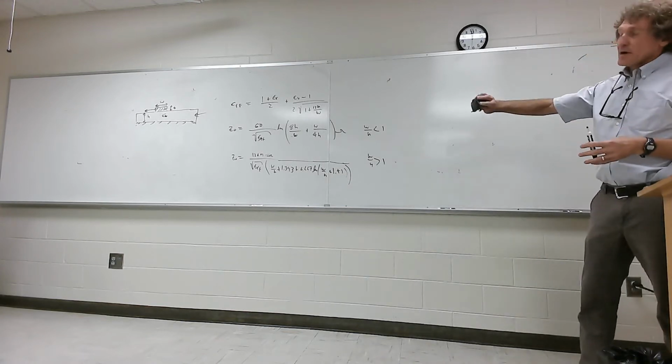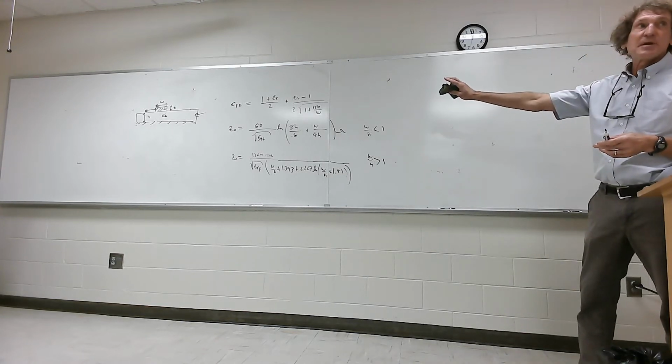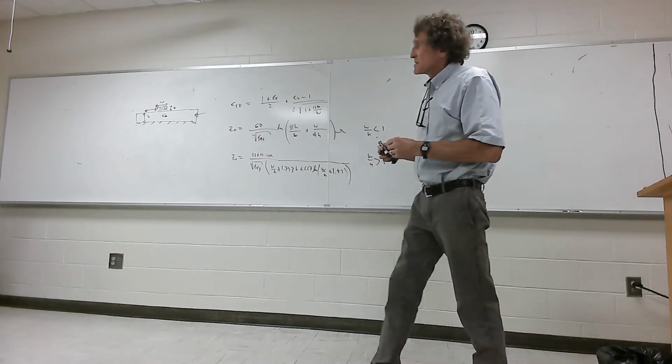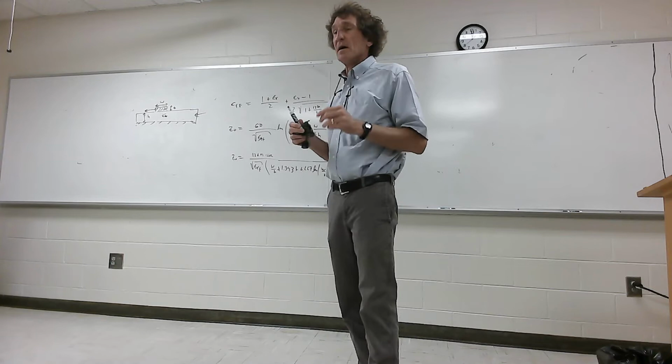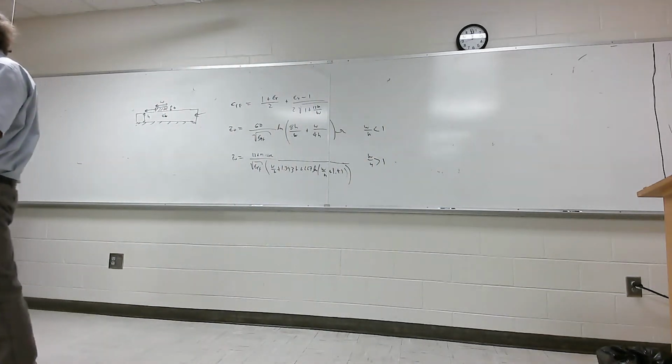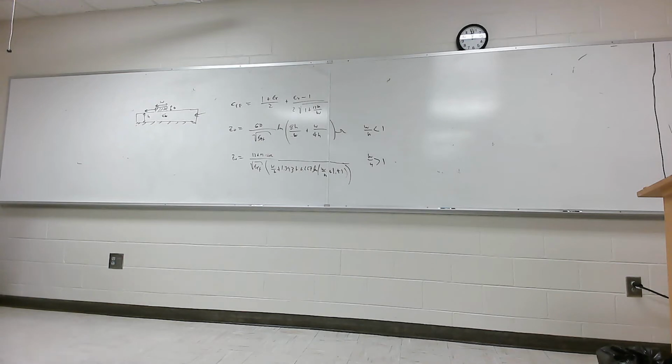So anyway, you don't have to know these, but you should at least be aware that these are some of the formulas that we use in the design process. And typically, there's one other thing. Now, can you think of one of the constraints when we talk about transmission lines back in EMAG 1? What is the difference between a straight piece of wire and something that could be viewed as a transmission line? Yes, but the length has to be greater than 1/10 of a wavelength. Do you all remember that? So for these things,